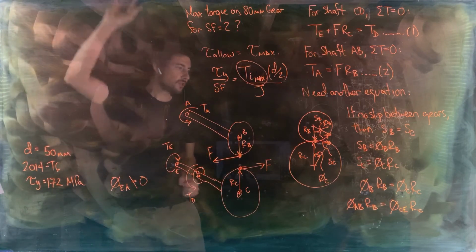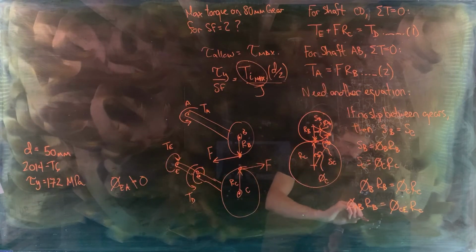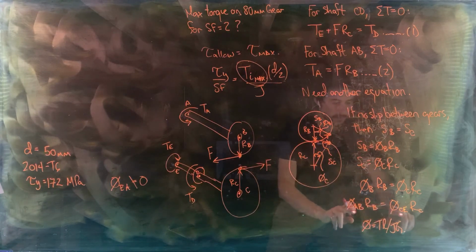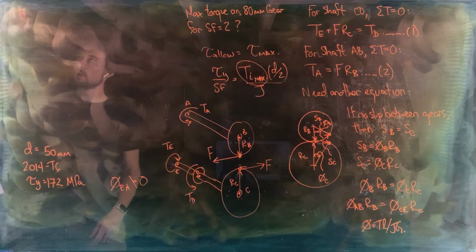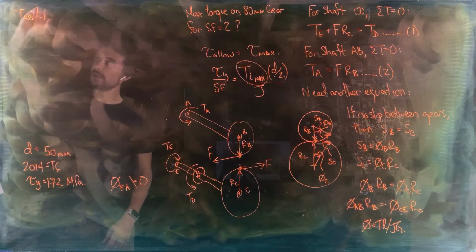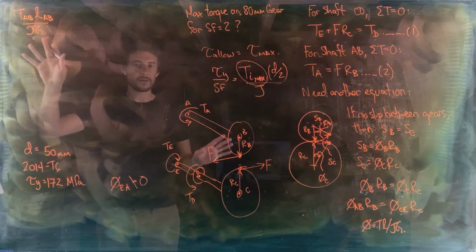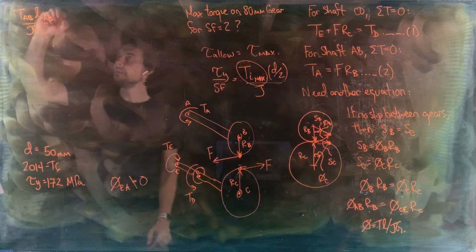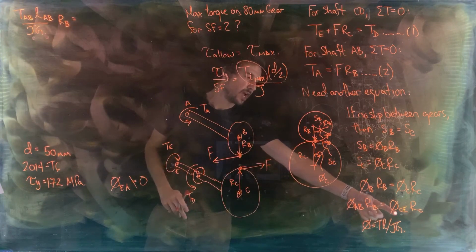Okay, so let's continue this equation. We'll use the angle of twist equation that we have. Phi is equal to TL over JG to expand both of these terms out. So phi AB is going to be the torque in segment AB multiplied by the length of segment AB divided by JG. Again, leaving subscripts off those because both shafts are the same material and same cross section. Radius of B on gear B equals the same quantity for shaft CE.